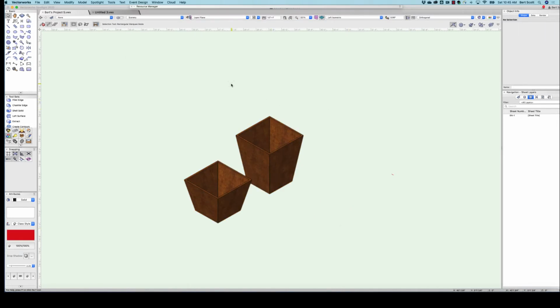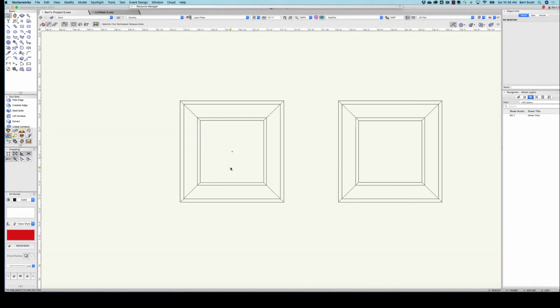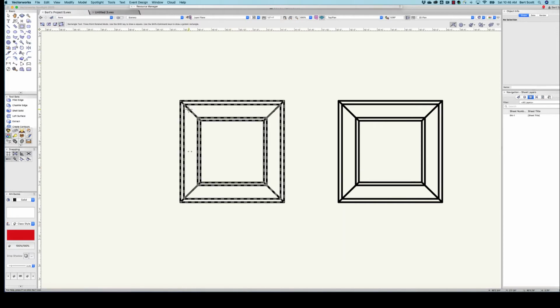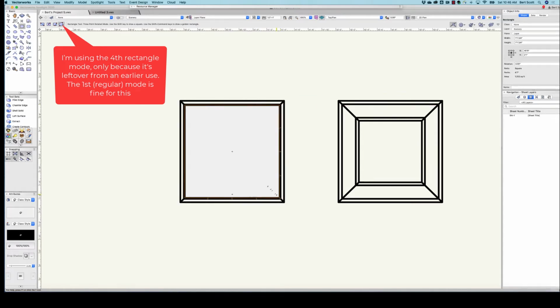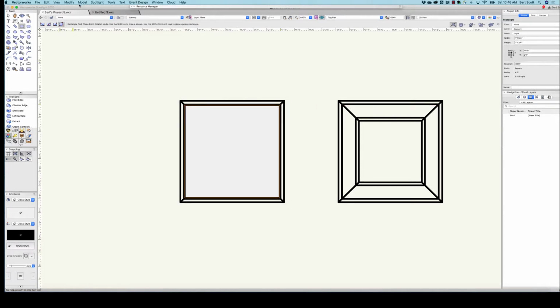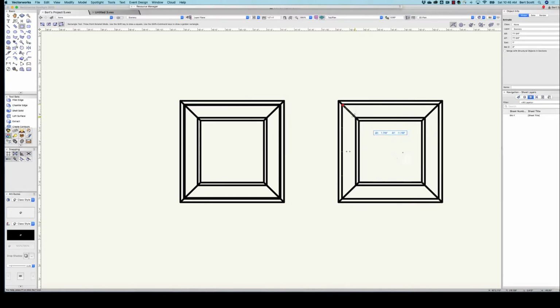Then before we add the plants in, we need to give them some dirt, basically. So in order to do that, we're just going to extrude a rectangle at the top here. It can really be any size, but let's just do 1 inch. So model extrude 1 inch. And then we'll do the same thing over here.